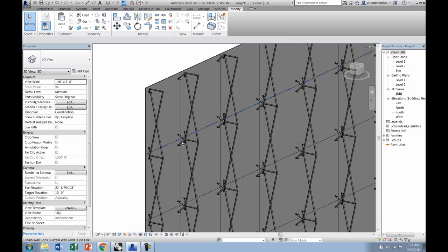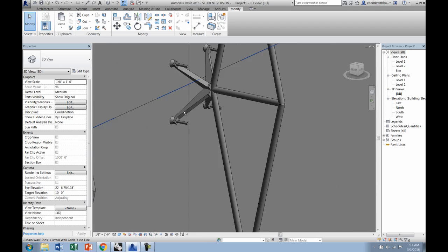As we start going in, any generic model that we open up is going to have an X, a Y, and a Z reference plane. Those planes can be locked to other reference planes as you bring them in from object to object. In this version, I'm going to try to minimize how many families we make and do quite a bit of it all in the curtain panel pattern-based family type that we'll do at the end to put everything together. That way it'll allow you to visualize what you're doing along the way inside of a project file.